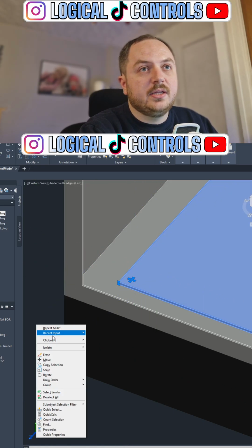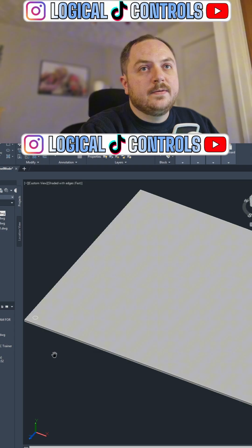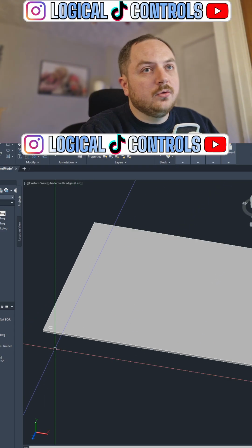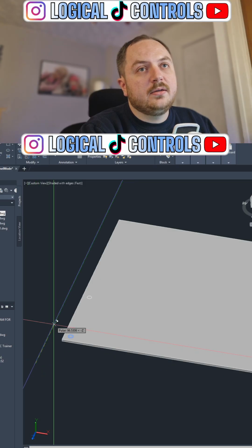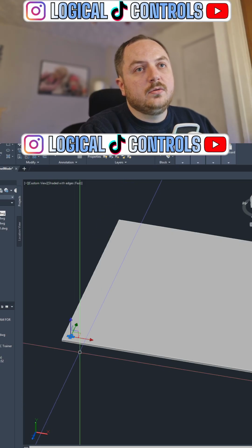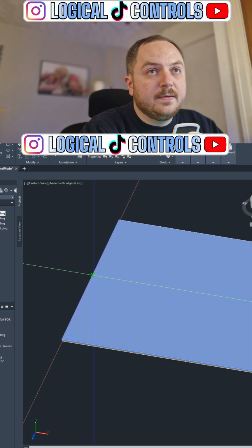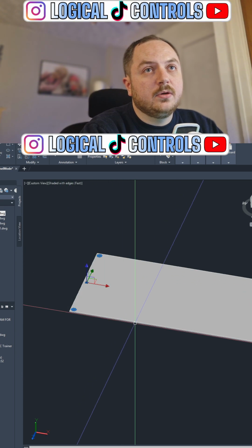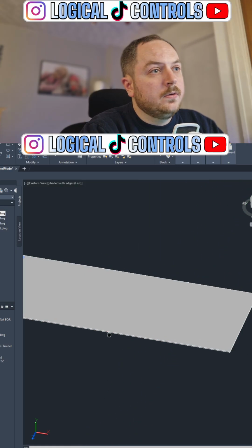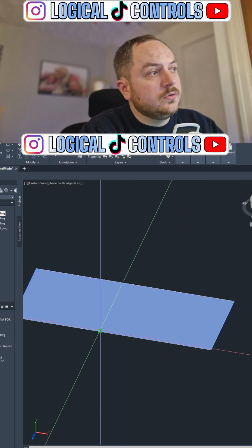So we're just looking at this to try and keep the focus on the aluminium gland plate itself, and we could copy that. In fact we won't, we'll mirror it. We'll find the center point and we're just going to mirror it like that, and then we're going to use them two, and hopefully you can see this all at once.